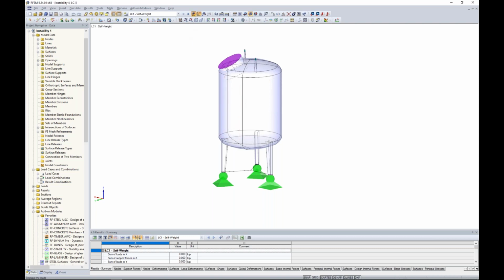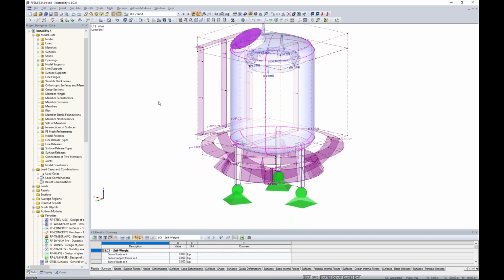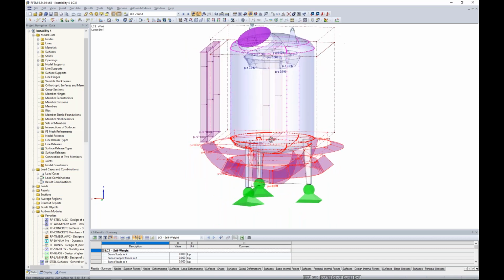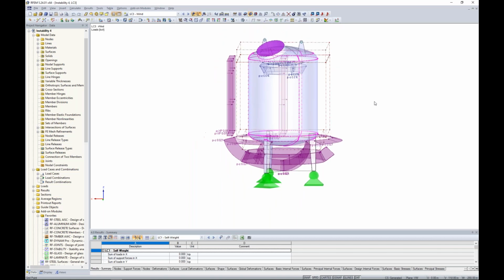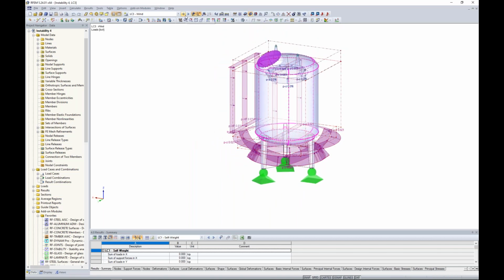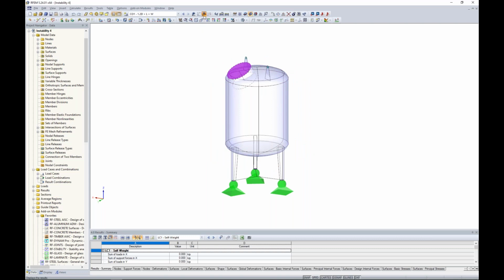So when I take a look at my applied loads, we have our first load case, which is just self-weight, so no additional loads are shown here. Then we have our fill load. So this is going to be an internal load pushing out on the structure walls here. And we have a wind load, which includes an uplift from the bottom and also a lateral load coming from the left with a suction force over on the right-hand side. So taking a look at my load combination where I've applied all three of these load cases together, we'd like to begin our first analysis.